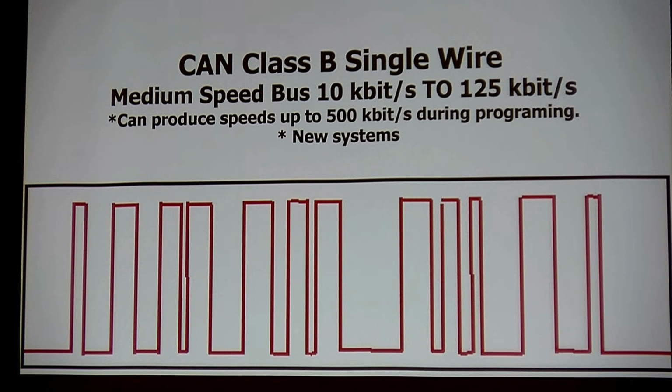I've only got 125 kilobits on the thing. So if I tie my bandwidth up, I limit the amount of messages that I could carry. So they just eliminated that. They say we don't need to know if you talked or not. But you need to understand how all of a sudden you got a dead module without one code in it, how that happened. That's why. But on a high-speed bus, that would never happen.